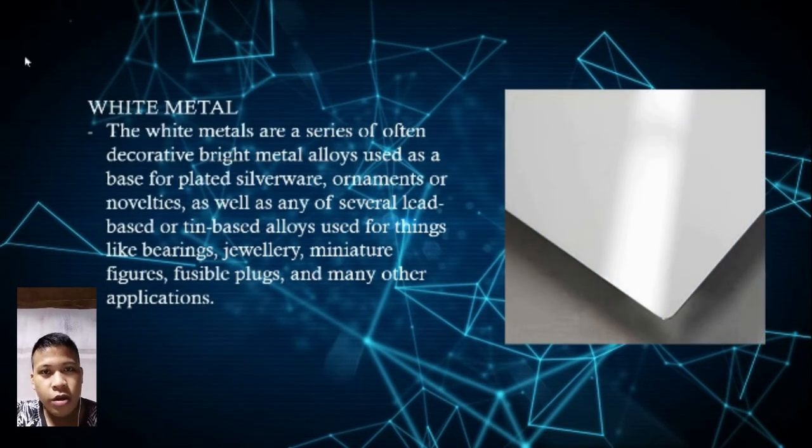The reason why white metals are used for bearings is because when there is an alignment or lubrication problem, the white metal bearing can compensate with greater ease than other types of bearings. The alloys used in white metal bearings are also called babbitt metals. These metals have a low melting point and offer very good resistance to friction.